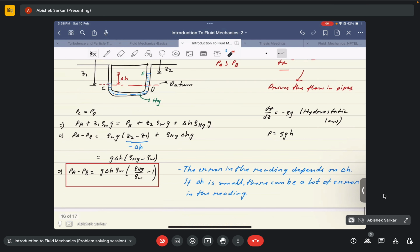Now just rearrange the terms, take PB here, so PA minus PB, because PA is greater in our case. Then rho W into G into Z2 minus Z1, this term will go there, and finally we have rho Hg into delta H into G. So this statement is clear.